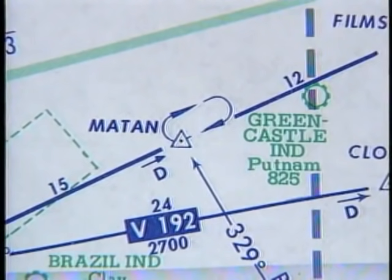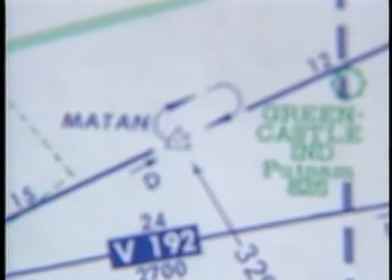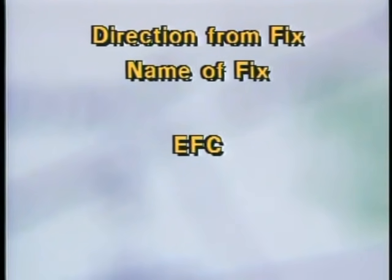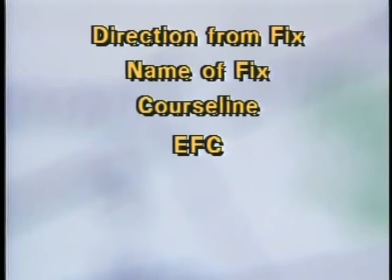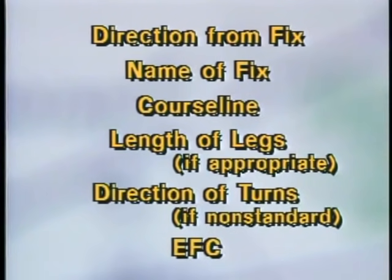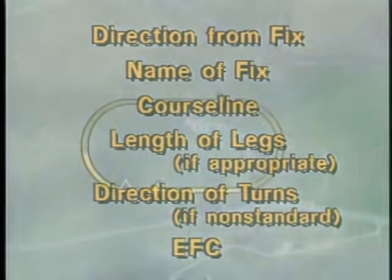If there is no published holding procedure, ATC issues a more descriptive instruction. All the items in the previous clearance are given except for hold as published. Instead of this phrase, you receive a description of the course line you're to hold on, the length of the legs if appropriate, and the direction of the turn if you're to use a non-standard holding pattern.